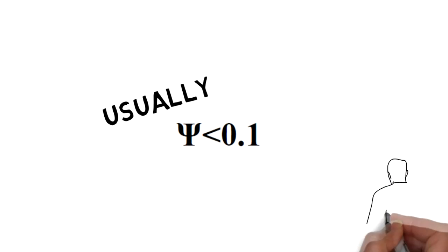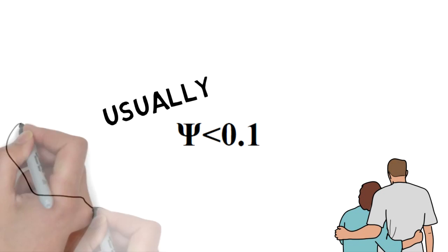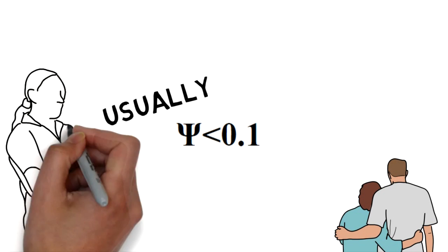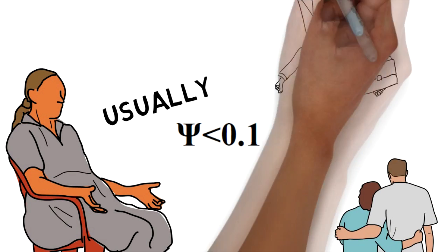Usually, fractional entrainment less than 0.1 is desirable. And since our actual flooding is below the design flooding value of 80%, our assumptions are valid. However, the optimum design value may be above this.